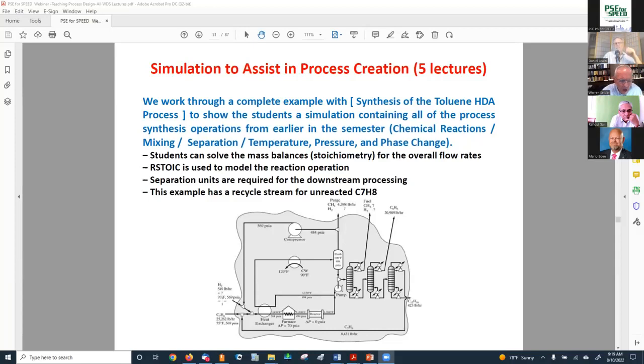So in this case, you would have hydrogen coming in. You would have toluene coming in. You are going to dealkylate. You are going to then make benzene and methane. Okay, so it goes into the process, and you can then determine what the product flows are going to be. I won't go through all that. That's just a mass balance. Now, when it comes to simulating the reactor, we have them do it simply with a stoichiometric simulator, okay, as opposed to a plug flow reactor.